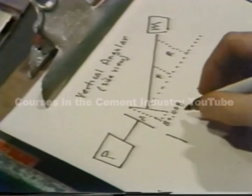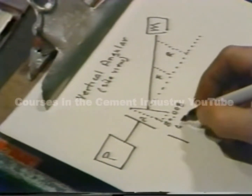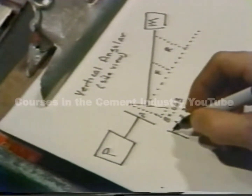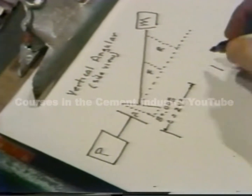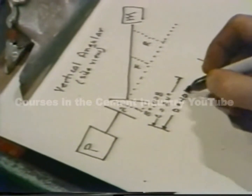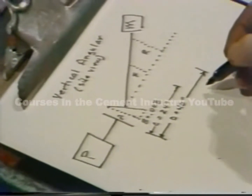The distance from the dial post to the front feet is 24 inches, and he labels it C. The distance to the rear feet is 40 inches, and he labels it D. He now has all the information he needs to make the calculation for movement.